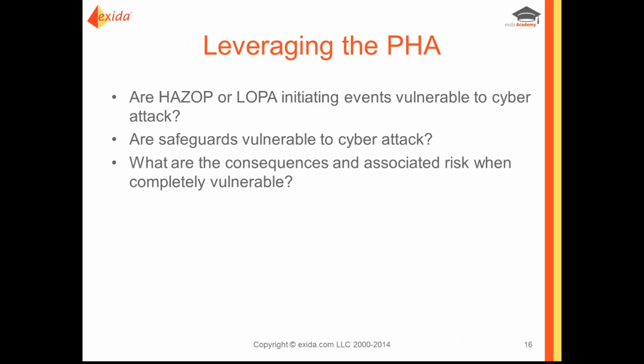So we want to leverage that process hazard analysis and start asking some questions. Are the HAZOP or LOPA initiating events vulnerable to cyber attack? So are any of these protection layers that you put in place vulnerable?